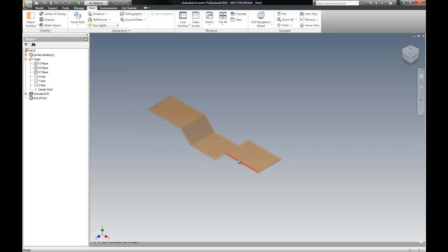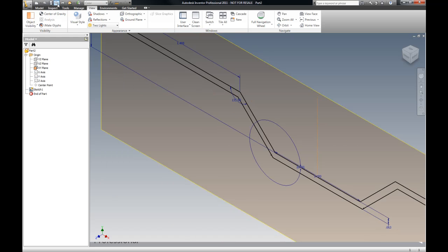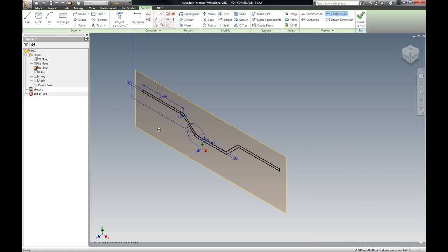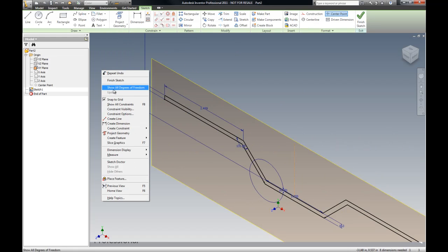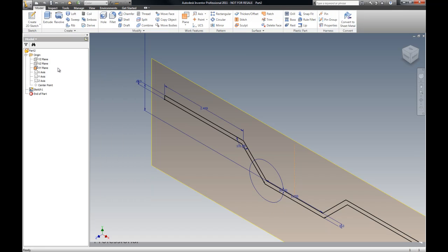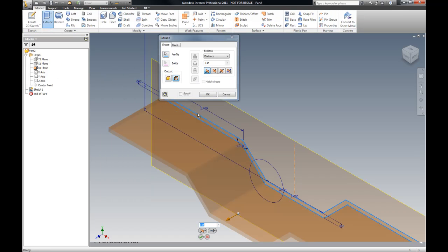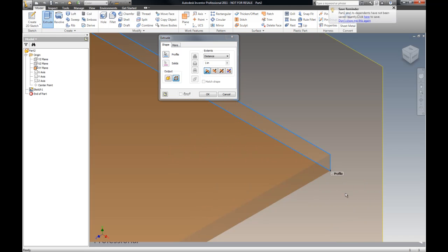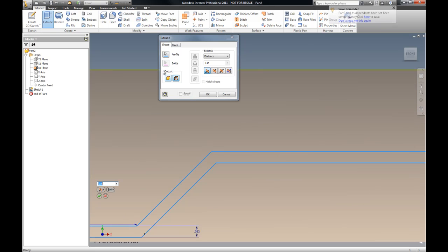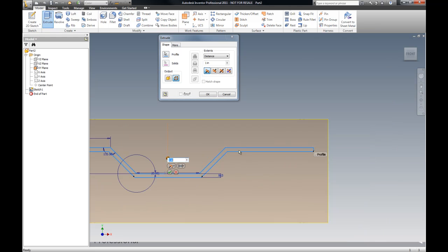And do you see what happened here? Can you see what happened here? I extruded only the edges, so we're going to have to back up here. When I did my extrude on this, I did not pick the interior, I picked all the edges. Get into the front here and see if I can pick the interior. And it's not going to let me extrude. So what that's telling me is I've got some geometry that's wrong.